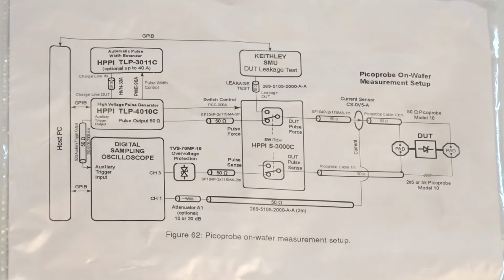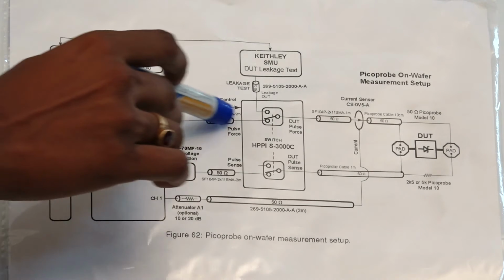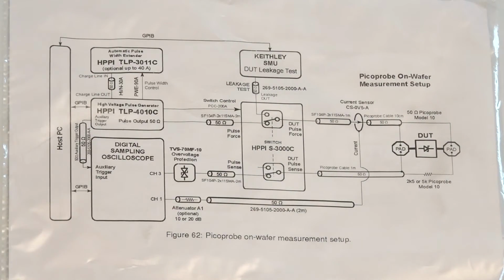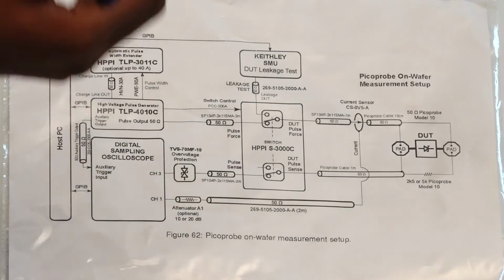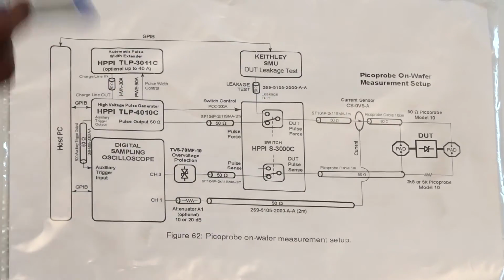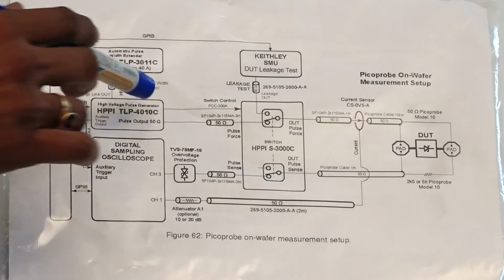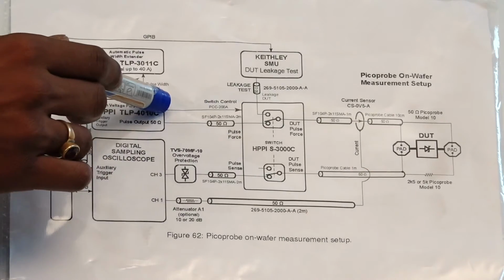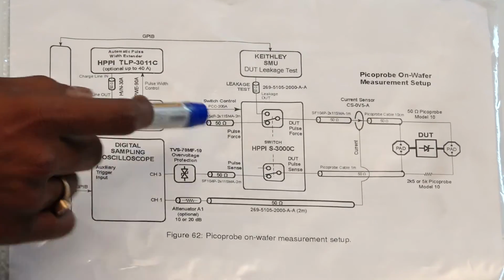Through a transmission line. The importance of the transmission line, and why we are using a transmission line everywhere here, is that a transmission line has a fixed impedance. Now you don't want a lot of impedance mismatch in the whole circuit, because as there will be more and more impedance mismatches at different points, there would be both reflected and incident waves. Say for example, if I were to use a random impedance here, that random impedance would lead to a lot of reflected waves, which I don't want, one. And then secondly, I will not be able to measure how much of the incident wave is getting reflected because of the impedance of the transmission line.